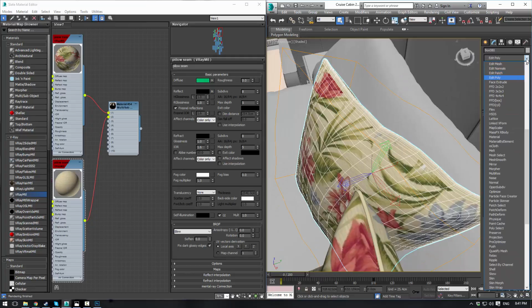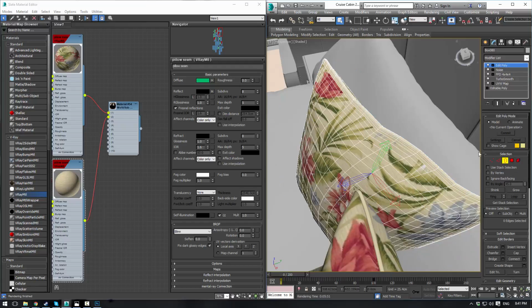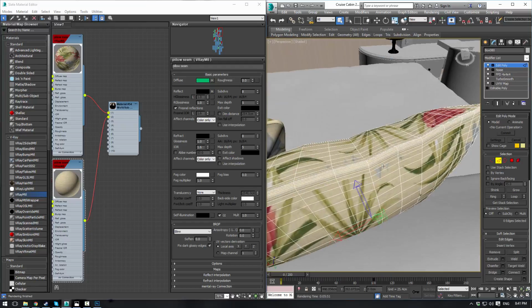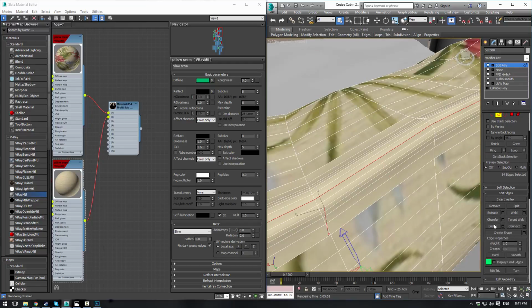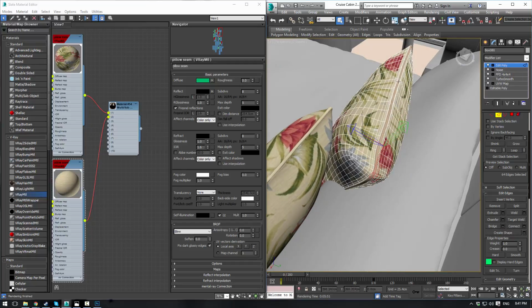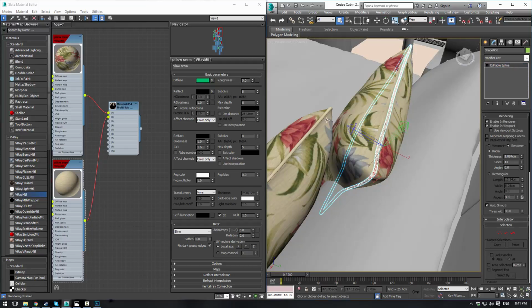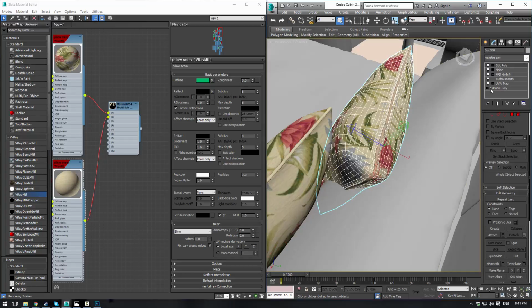So, edit poly. Alright, go to the edge selection mode. Grab basically the middle edge, loop it, create shape. There's your seam. Make sure your radius of the seam is the same. So, as an example, this radius is 1.894, and this is 1.894, so we're good. So go back down here to your polygons,